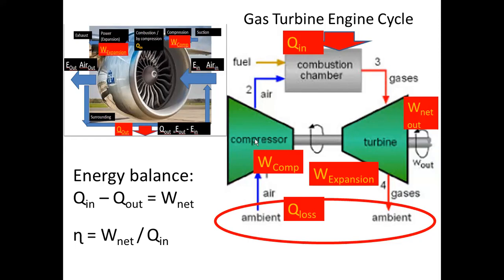That is one thing. And because of the fuel: air from the ambient goes through the compression process, and the high temperature compressed air interacts with fuel. That is a huge fire. That makes it possible for the turbine to run. And finally, exhaust gas comes out. So air goes in, gas comes out. Compression is air, expansion is gas. We may call this a gas turbine, but if you ask what the working fluid is, I would say the working fluid is air, because the intake is air and the compression is air.